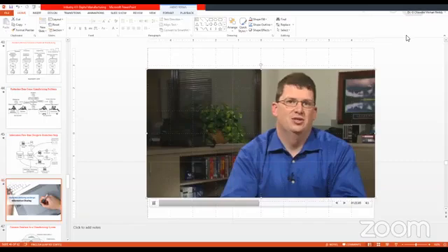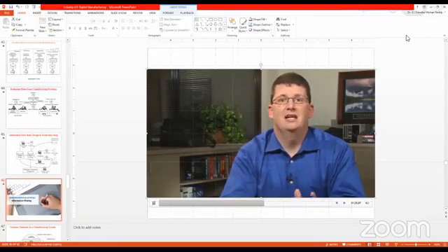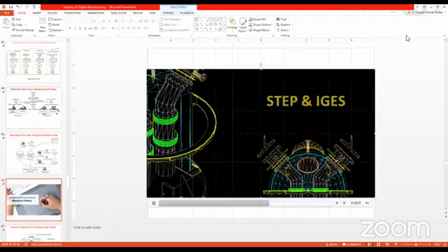That's what data standards do. They specify a consistent data format so the data can be shared and transformed into usable information. Some examples: STEP and IGES are data standards for sharing product design data like geometry. These are the file formats in which it is shared. MTConnect is a standard that supports the capture and sharing of information from machining equipment.